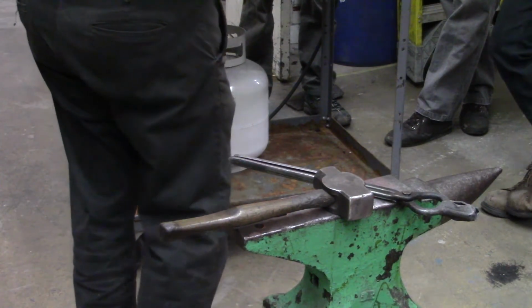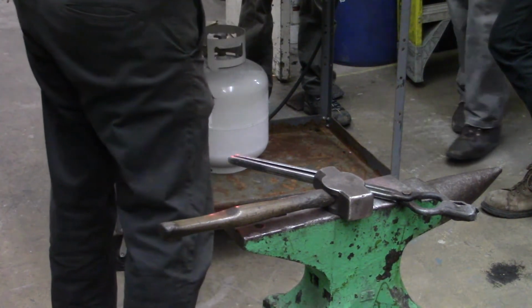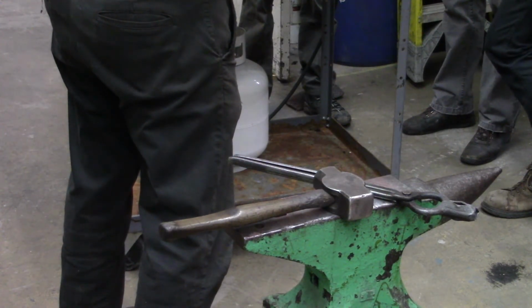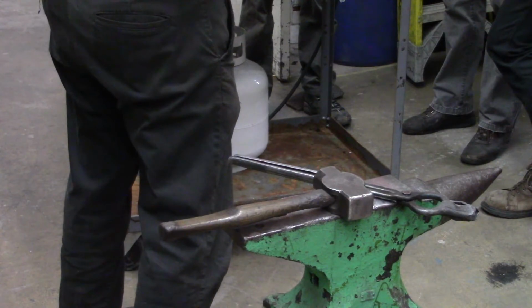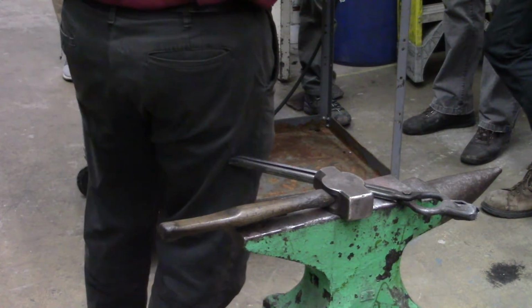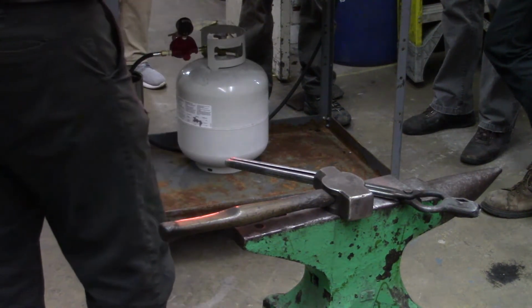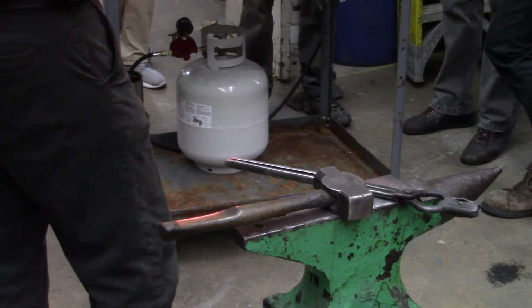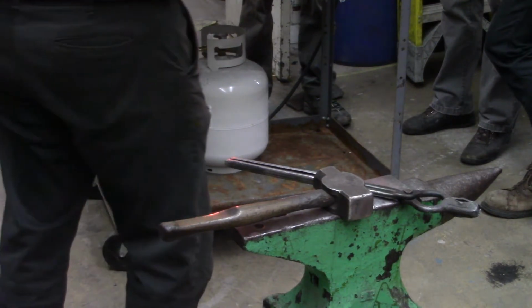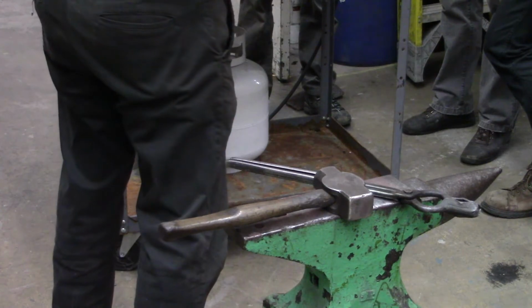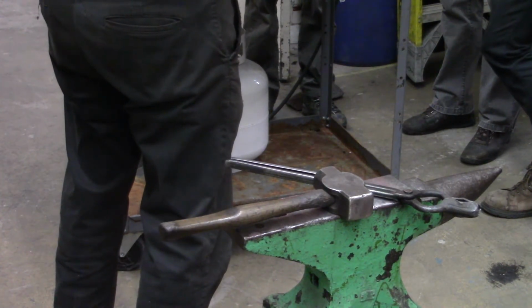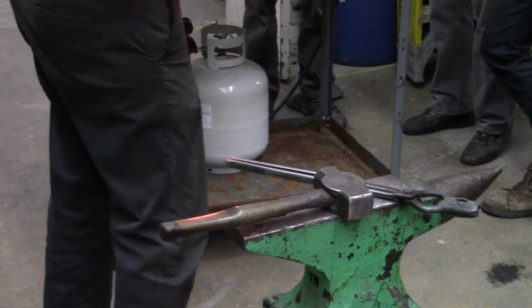So just curious, if you were to peen the end over, how would you go about that? I mean, you're basically upsetting the material. So you have to support the end. Clamp the knife in a vise, or on something that's hard but not marring, like a wood block or something like that. Yeah. And you might even take a small torch and heat that piece a little. Okay, that's what I was thinking. Yeah, yeah.